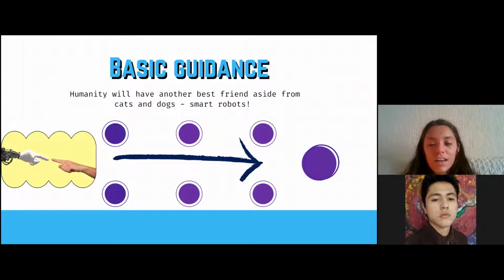The robot is guided consecutively through the desired points during the automatic execution phase of the program. During this phase, the control unit interpolates these points according to certain trajectories. In many cases, it is not possible to include any kind of control structures within the program. So the points are always traversed sequentially in the same order in which they were programmed.